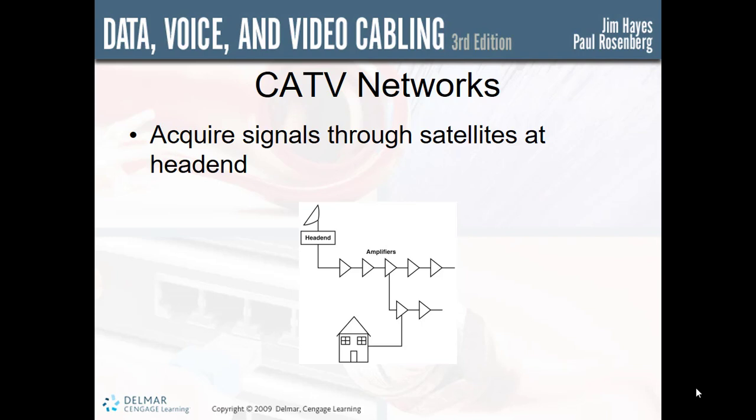These cables terminate in amplifiers that rebroadcast it over many other cables to more amplifiers, which repeat the rebroadcast. Thus, the CATV system looks like a tree and branch system, the name used to describe the network architecture. The obvious fault of this type of system is its vulnerability to the failure of a signal amplifier. If any amplifier fails, service is lost to all the downstream customers. The solution then would be to separate the network into smaller segments to prevent massive failures.